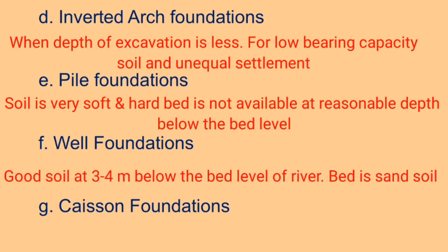Sixth one, well foundations. This type of bridge foundation is suitable where good soil is available at about 3 to 4 meter below the bed level of the river and the bed consists of sandy soil.